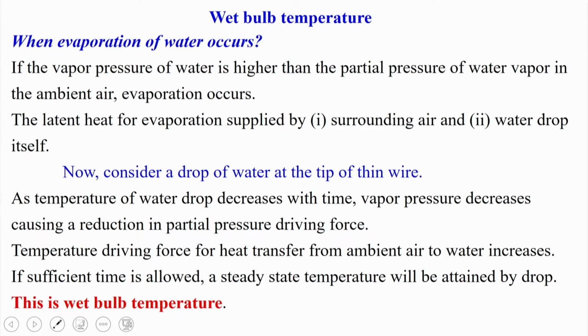Now, we need to consider one drop of water at the tip of a thin wire. Suppose one water drop is hanging from the thin wire. As the temperature of the water drop decreases with time, vapor pressure decreases, causing a reduction in the partial pressure driving force, and the temperature driving force for heat transfer from ambient air to water will increase. So, if sufficient time is allowed, a steady state temperature will be attained by the drop,